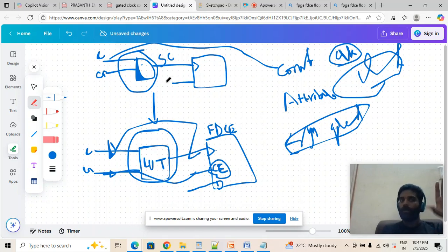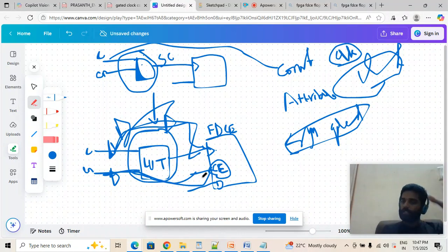So if the ASIC RTL has this gating logic, the tool itself will directly connect the clock to the register port, and this gating logic will go to the clock enable port. There will be a buffer in the middle; you can see some input buffer, a BUFG in the clock path, and for this gating logic only the input buffer will be there. It connects directly to the clock enable port. This is the general way the tool will understand and implement it if you give it a constraint.